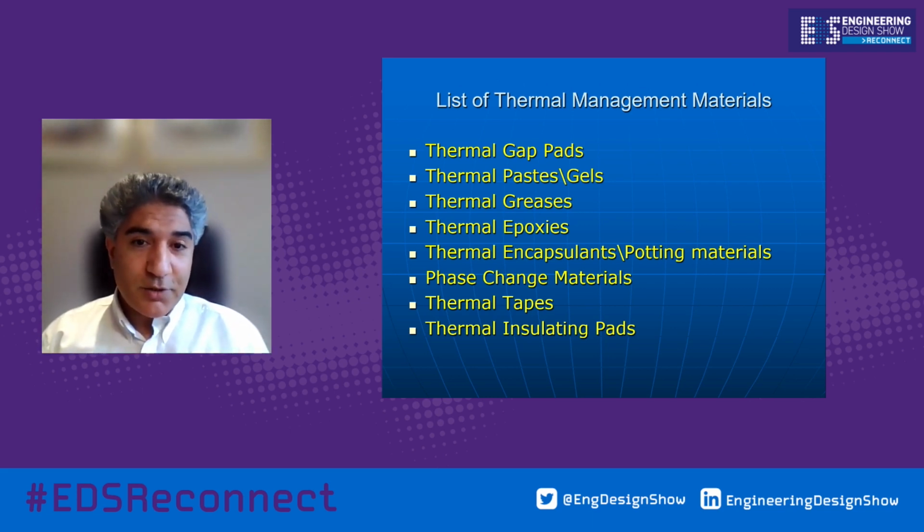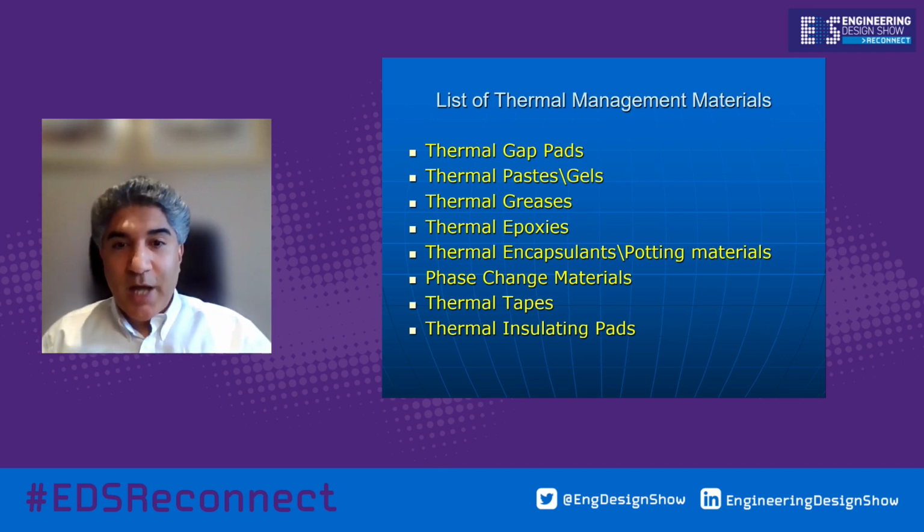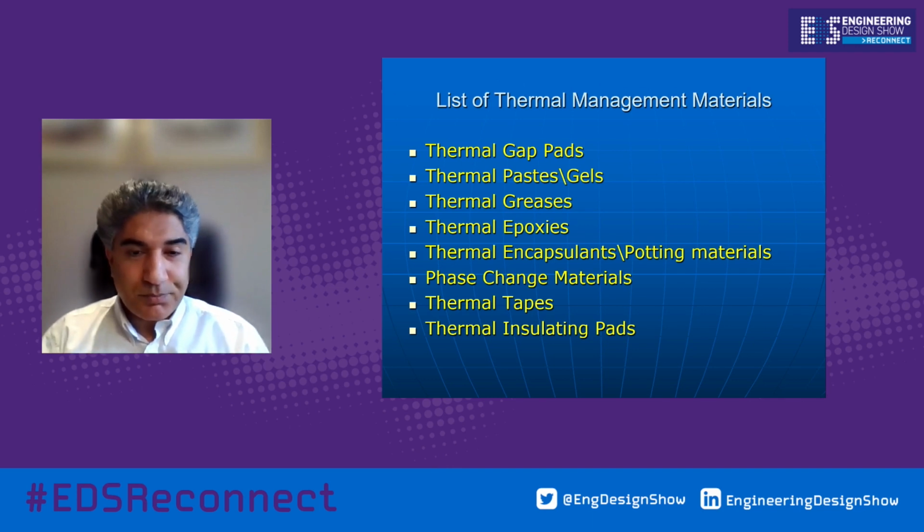HITEK also do thermally conductive encapsulating potting materials, the Stycast range. The Stycast 2850 range could start from 1.25 watts per Kelvin right up to 2.26 watts per Kelvin thermal conductivity. HITEK do that, and we also do down-packing if required.